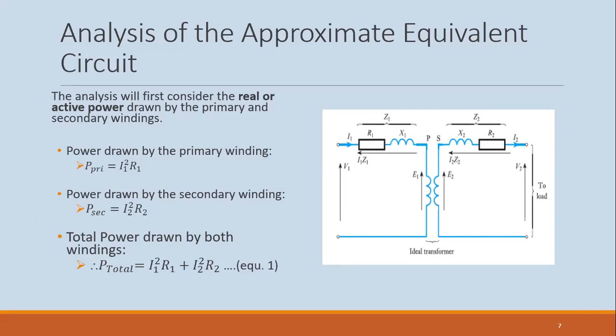Because I realized that at full load, the voltage would really be less than before. Right, than the rated. Right. That is what we're trying to show, that once you load the transformer, in reality, that is what will take place.